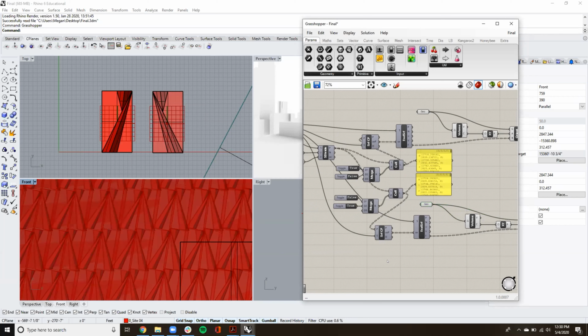Right now you're orientating it based off that point, right? But your modules aren't changing along that surface. What I recommend will take your module and put a box around it, which we call the bounding box. That bounding box will twist and deform, and it will change your module to fit on your surface.